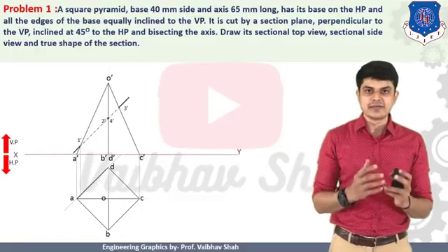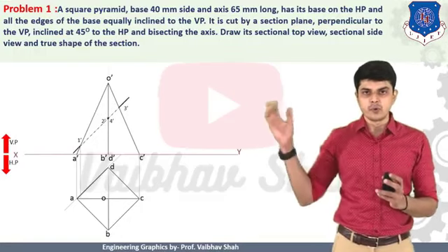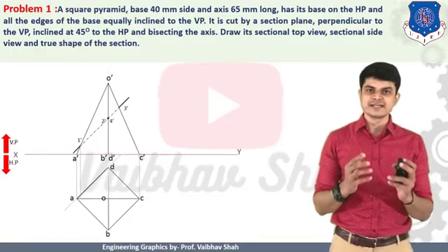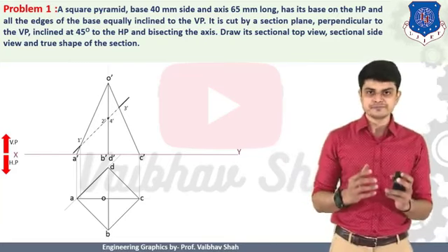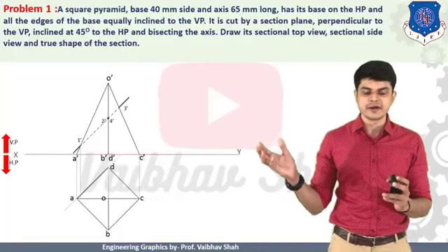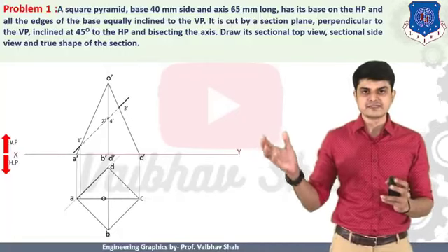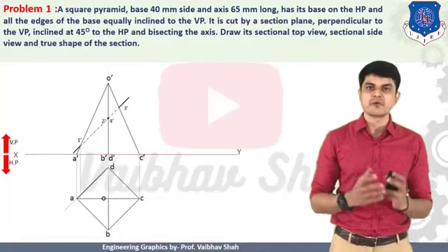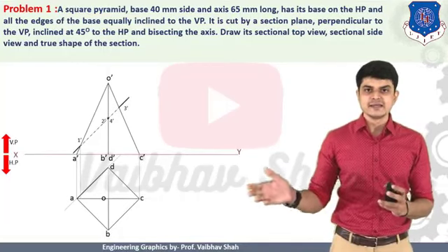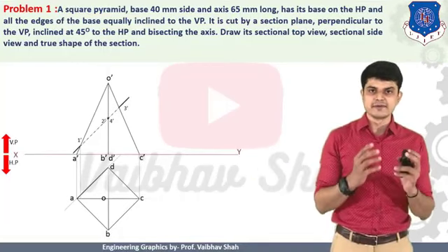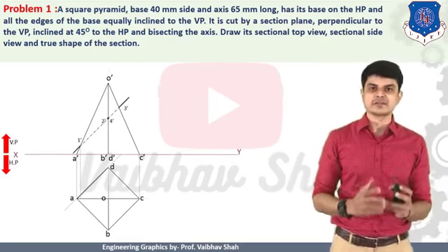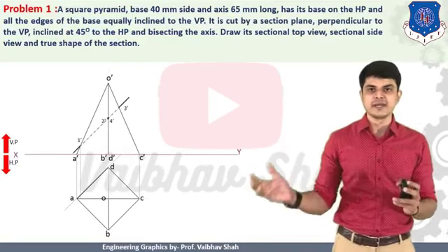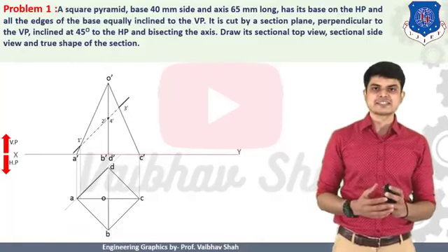Then we have the 2 dash point on the O dash B dash line. So we should vertically transfer the point 2 onto the line OB. Then we have the third point, which is on O dash C dash. So we should transfer this third point onto the OC line in the top view. And finally we have our fourth point, which is on what? O dash D dash. We should transfer that point to the line OD in the top view.